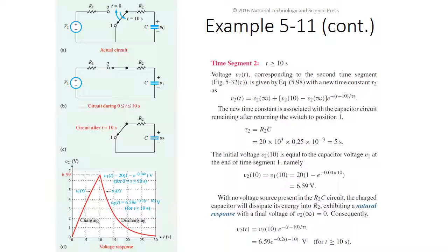But the picture is going to show you that sharp increase of voltage while you're charging, because essentially the circuit starts as uncharged. As soon as you flip that switch, that voltage source is going to start charging that capacitor based on those resistors and how high those resistors are. And then once it gets to that certain point, we're going to flip it, and it's 10 seconds, so it's not fully charged, so we never plateau out. This doesn't show a plateau. It shows a start peak and then a decrease, which is your discharge.